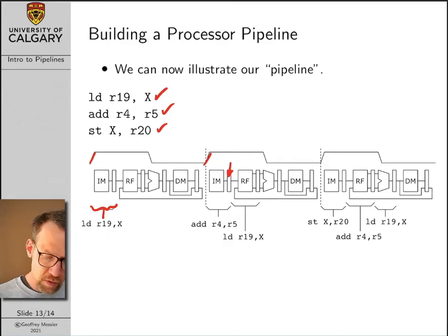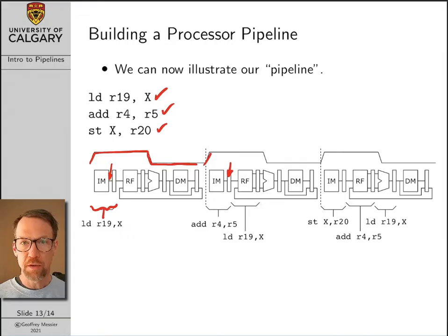So during this first clock cycle, the fetch has occurred. There was some instability at the output of our instruction memory as things settled out. But by the end of our clock cycle, the output of our instruction memory is stable, and we are going to use this first pipeline register to lock the result in place for our next clock cycle.